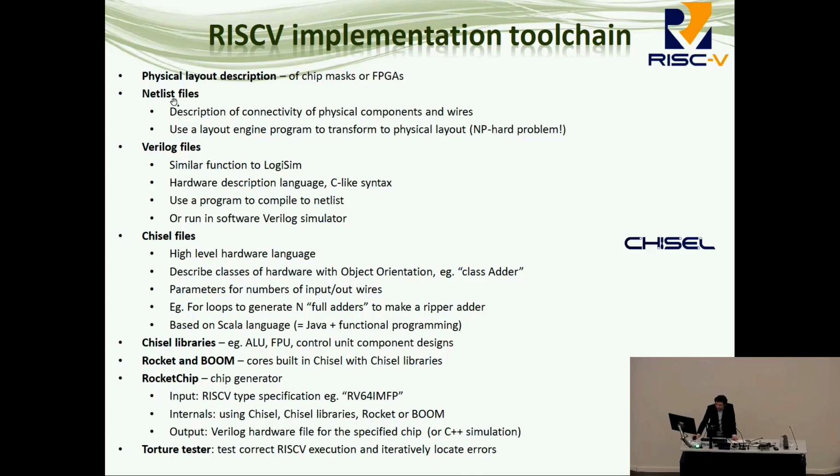Again, you wouldn't write your design typically as a netlist. We have higher levels still. You can go to a language called Verilog. Verilog is the more professional version of Logisim, the tool you've been using in the workshop. So we lose the graphical interface from Logisim. We write what looks somewhat like an XML file, somewhat like a C file. It's a text file describing, again, what is connected to what, but it gives you a higher level view than a netlist. You can create structures in Verilog. So if you create something like an adder or a half adder, you can work with blocks at that level. So you'll take a compiler that runs that to a netlist and then compile that again into your physical layout.